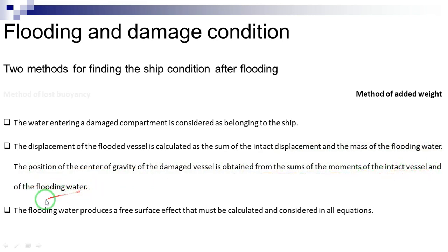Becoming part of the vessel, the flooding water produces a free surface effect that must be calculated and considered in all equations. Note that since the added weight method involves a direct integration of volumes up to the damaged condition waterplane, it is just as well adapted to dealing with complex flooding conditions as with simple ones. For greater accuracy, or where complicated flooding configurations are involved, added weight calculations are recommended.